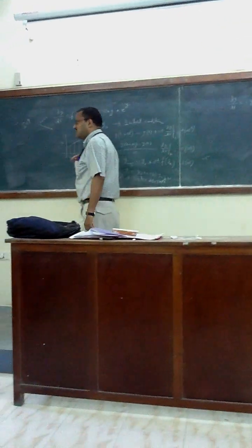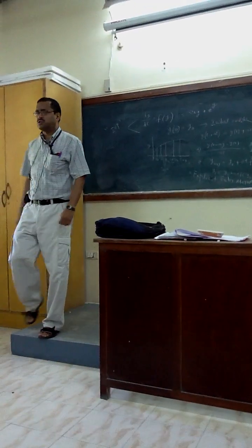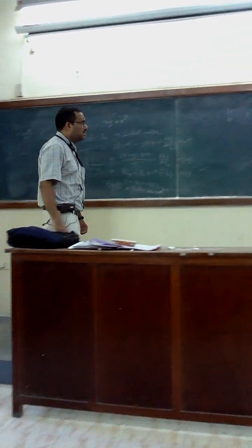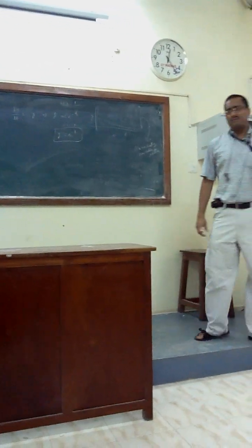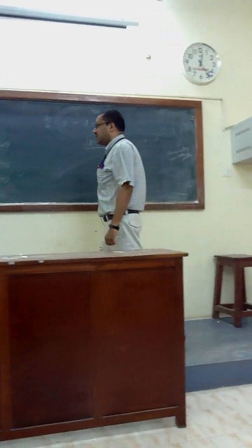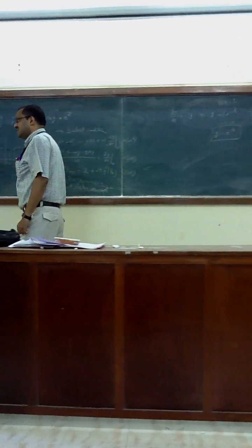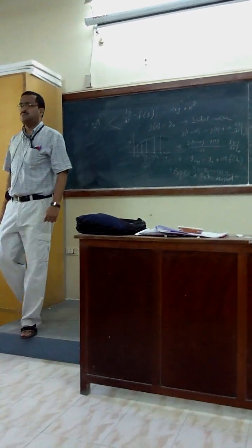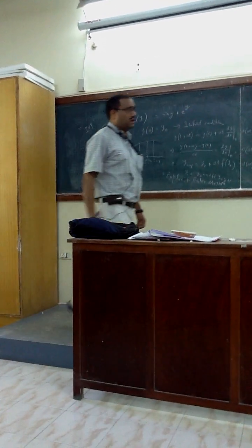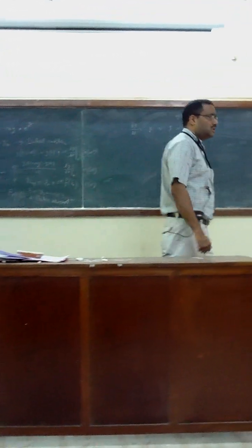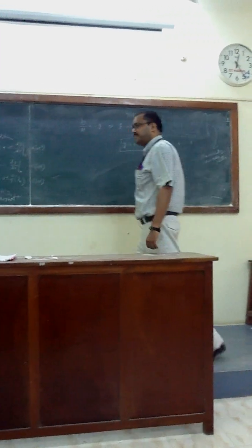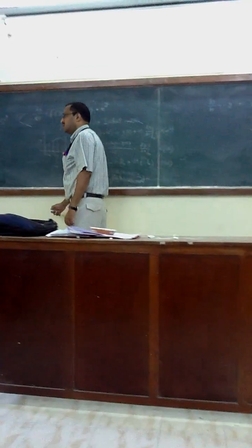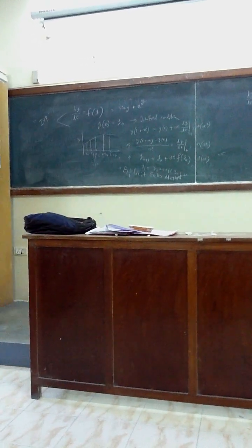Although this method is very easy to implement, it has serious issues of numerical instability. In that case, you need to have very small delta t. Otherwise, you can get a numerically unstable problem. That means what? Explicit method is easy to implement, but it is conditionally stable.